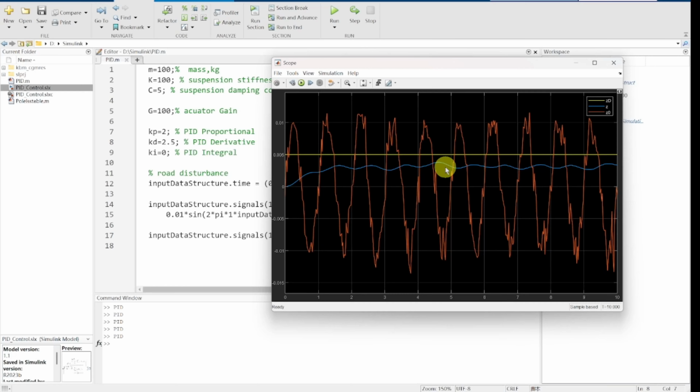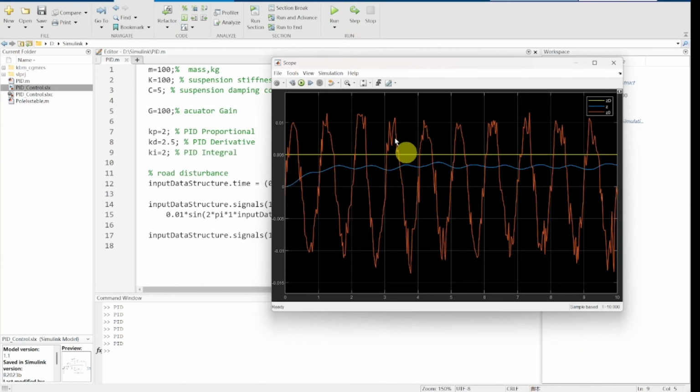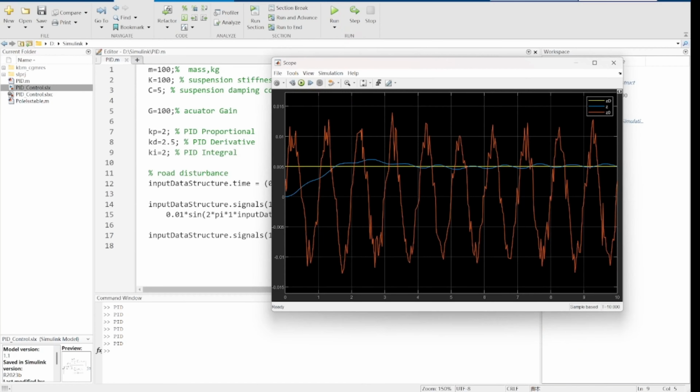So, how do we close the final gap? We add I, integral, and set its value to 2. Right? Refresh the result. Just like magic, the blue line now almost perfectly hugs the yellow target line. The role of I is to be relentless. It fights until the very end to completely wipe out that steady state error. That is the teamwork of PID.